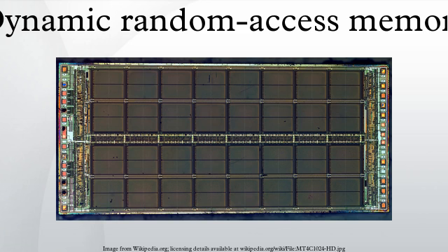Since even non-conducting transistors always leak a small amount, the capacitors will slowly discharge, and the information eventually fades unless the capacitor charge is refreshed periodically. Because of this refresh requirement, it is a dynamic memory as opposed to SRAM and other static memory. The main memory in personal computers is dynamic RAM.